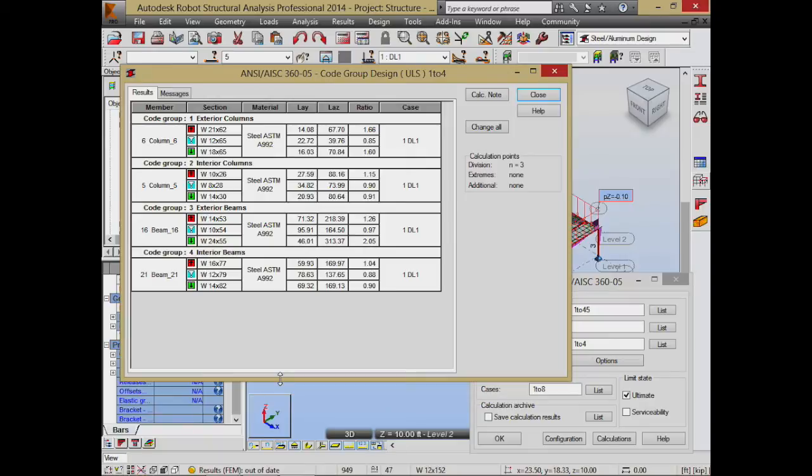So what we'll do now is go through and look at the interior column. It's interesting, 12 by 65 over there, 8 by 28 over there. Well, that strikes me as being very odd. Exterior beams 10 by 54, interior beams 12 by 79. That strikes me as being right. This strikes me as odd. I've got to think about what's going on, if somehow we're torquing things in some funny way, because that seems like a very funny number. I want to dig into that one some more.